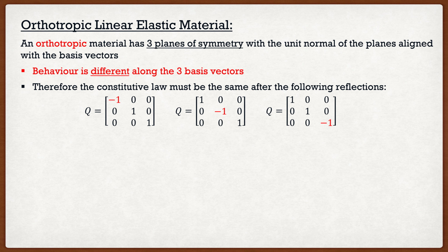Now, this is where things kind of become a little bit of a problem when we're trying to think of just matrices rather than tensors. So remember when I say the stress tensor and the strain tensor, I said for your purposes, we can interchange those with matrices for this course. But this becomes a problem when we start to realize, well, I'm trying to transform a 6 by 6 matrix with a 3 by 3 matrix. It makes no sense. So what we're actually going to have to do is realize that this C, this stiffness matrix, it's actually a 4th order tensor.